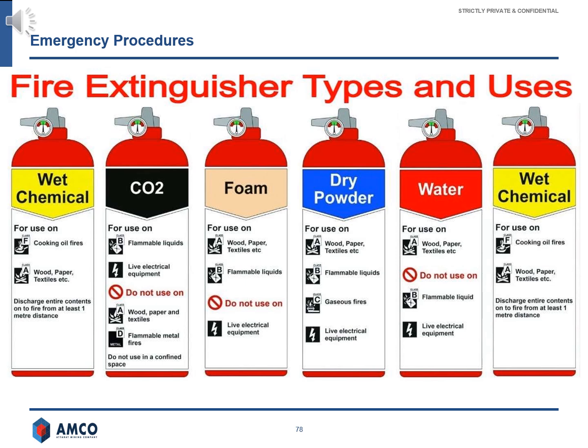For electrical fires involving live equipment, it's crucial to use the correct type of fire extinguisher to avoid the risk of electric shock. Suitable fire extinguishers. CO2, carbon dioxide, extinguishers are ideal for electrical fires as they do not leave any residue and do not conduct electricity. They work by displacing oxygen, which helps to smother the fire. Dry chemical powder extinguishers contain non-conductive chemicals that can effectively put out electrical fires without the risk of electric shock. Unsuitable fire extinguishers.